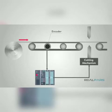Encoders will use motion under a variety of technologies and translate it into an electrical signal. That signal is then sent back to a controlling device, such as a PLC, and is interpreted, meaning scaled, to represent a value that will then be used within the program.